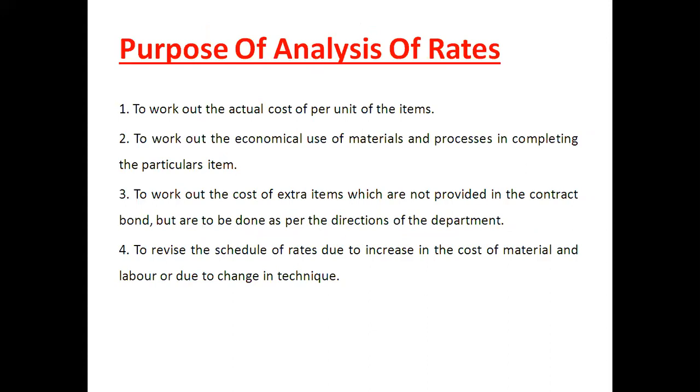Now, how it has been there, I can just give you one example. Suppose in your concrete, rather than casting a conventional concrete, you are going to cast a special category of concrete. Maybe it involves fly ash. We are going to replace our cement by fly ash. It's a basic change we can do, because fly ash has the same properties as that of cement. It's a good replacing material we have.